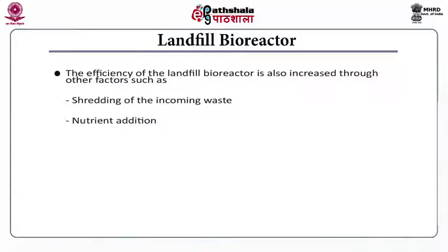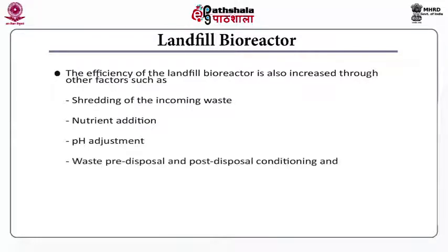Also, you can add nutrients through the incoming waste stream or through other modes of maintaining moisture. You can adjust the pH, and waste pre-disposal and post-disposal conditioning and temperature control will also act as factors to accelerate the rate of degradation within a landfill bioreactor.